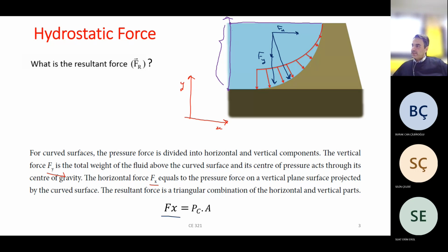Therefore, any pressure acting on this surface can be used to calculate Fx. I can find the projection of the pressure on this vertical surface, like this. Then I can use this diagram to calculate Fx.